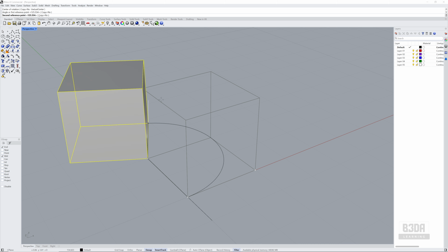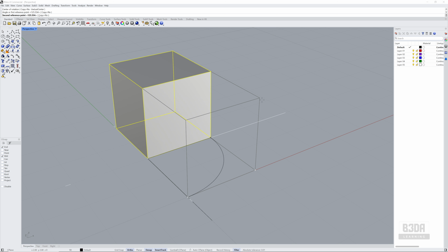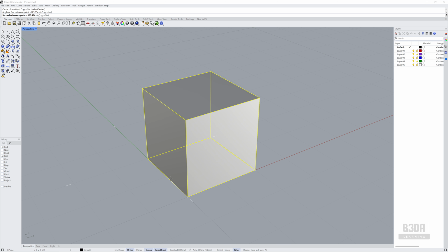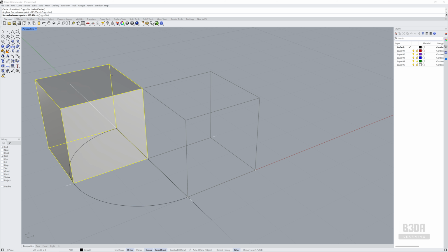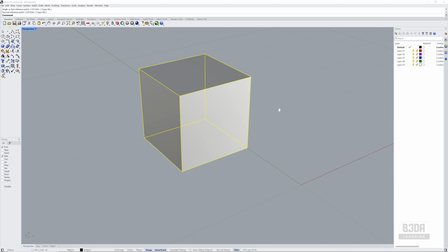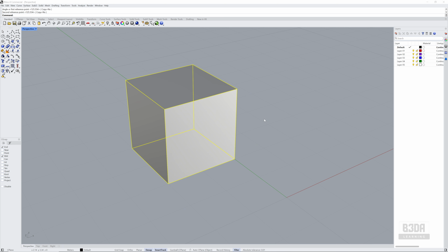And one cool thing about this feature is that you can either type an angle that you want, or if you press and hold the shift key, it will use an orthographic. It will jump 90 degrees. For instance, if I want to rotate 90 degrees in this direction, you just have to click here and it will use that reference. What if we want to use a 3D rotation?